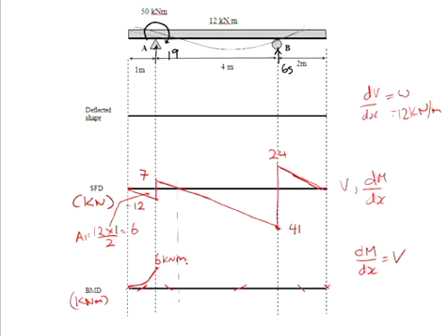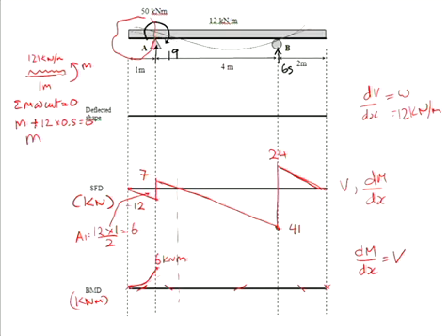Now, you also have the option where you can create a free body diagram, 1 metre long, and you want to know what this moment is at the cut, and your load is 12 kilonewtons per metre. So you can take moments at the cut, and you'll have M minus 12 times 0.5 equals 0. And I'm saying minus, and you should all be going, but isn't it a plus, Lizzie? Yes, it is. And from that, my bending moment is 6 kilonewton metres.